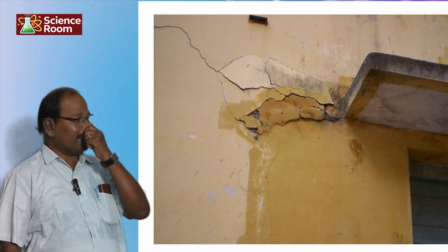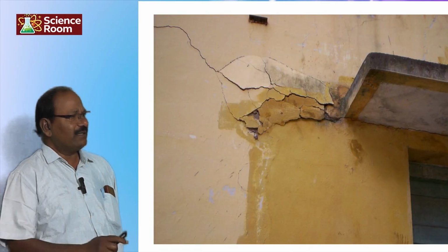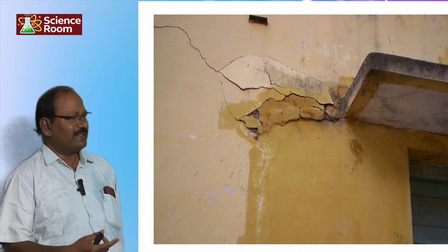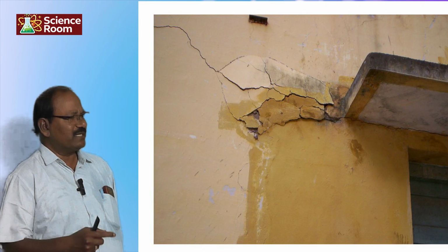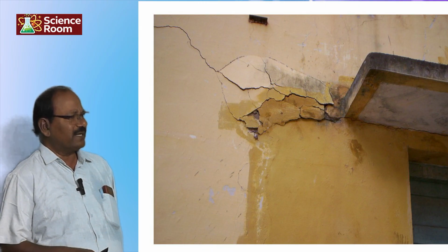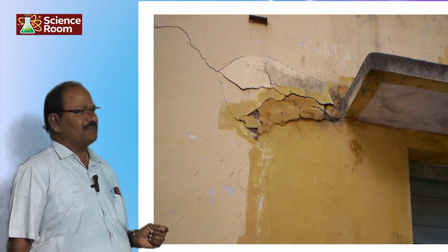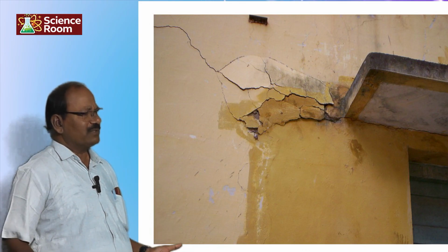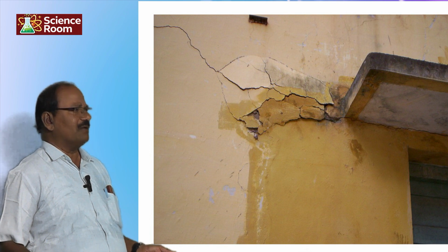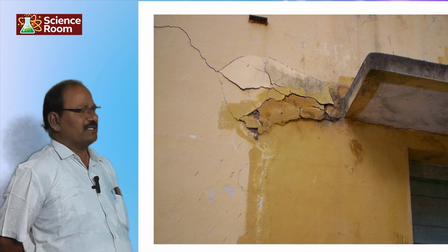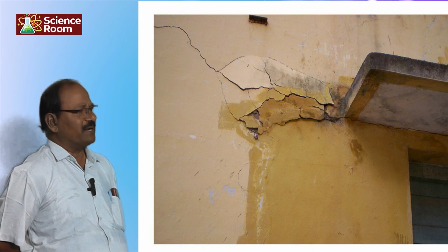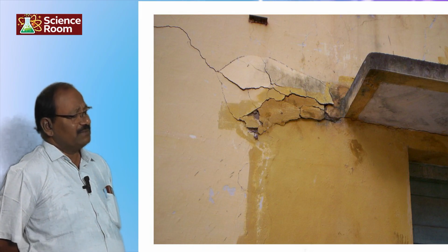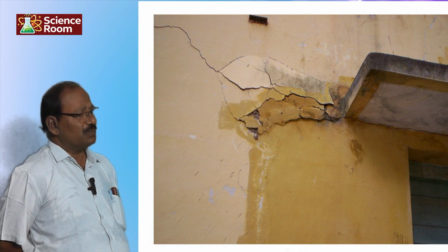Next, you see near the sunshade, the lintel concrete is affected. The water got inside, corrosion is initiated, and around the steel bar the corrosion has taken place. If 1 mm thickness goes into corrosion, it will produce 6.5 times the volume, that is, 6.5 mm of expansion. The rust product that is formed around the steel goes up to 6.5 times, and that induces stress called hoop stress.